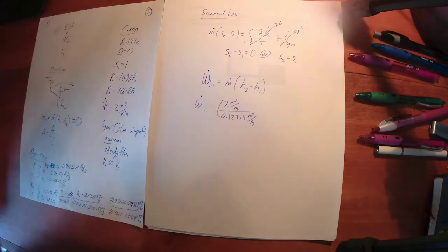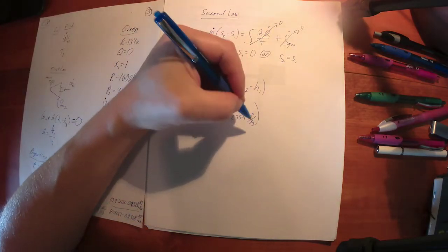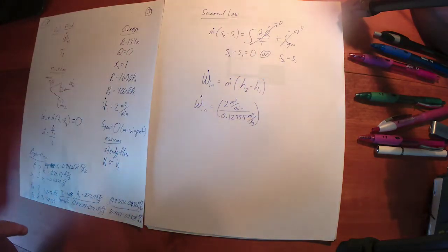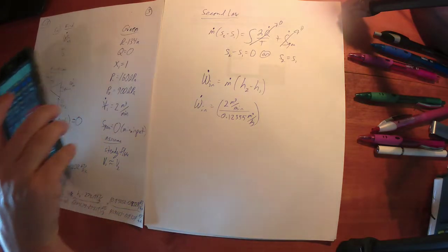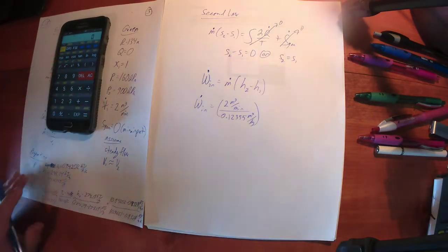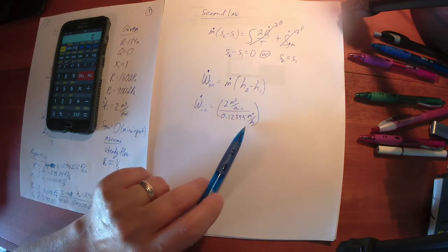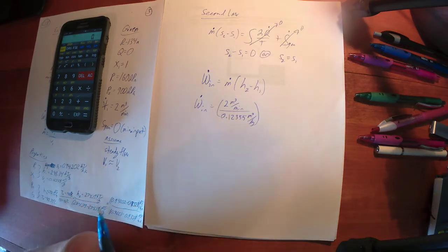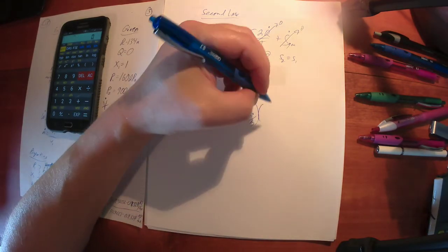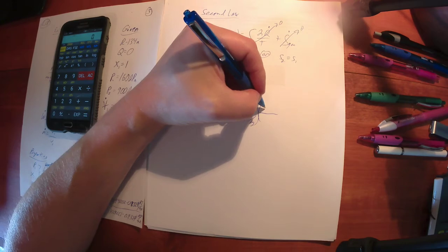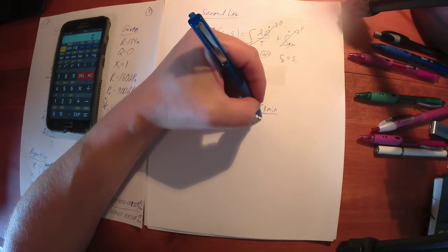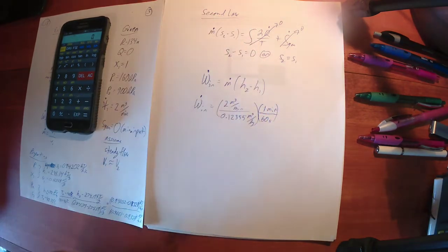And I get this question a lot of times about, Steve, do we have to write units in our calculations? No, you don't. You don't have to write units in your calculations. You just have to make sure the units work out at the end. So if all I've written here is 2 over this number, I'm not going to realize that this is kilograms per minute, which is not kilograms per second, so I'm not going to get kilowatts. To get rid of this minute here, I've got to multiply by 1 minute for every 60 seconds. Okay, then I'm going to get per second, and then the whole thing's going to come out.